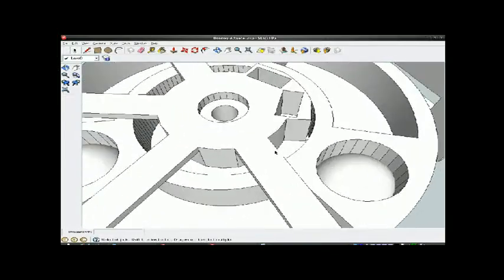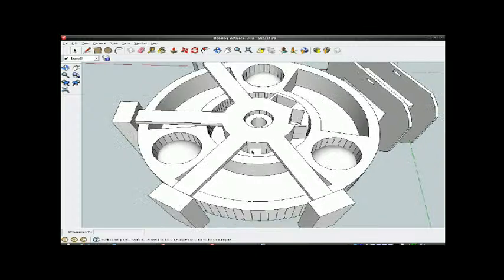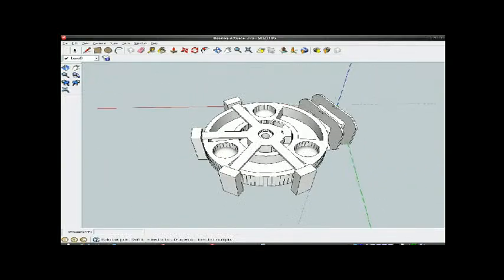And another advantage of having these holes is that you've got room to put counterweights and things to balance it out. So I could stick a bit of lead solder in there, if it was off balance I could easily put things inside it to balance so it doesn't wobble and vibrate. It makes it a lot easier, because otherwise I'd have to drill holes in it, and I don't want to be doing that if I can help it. So that's that. I made a little bit of progress today.